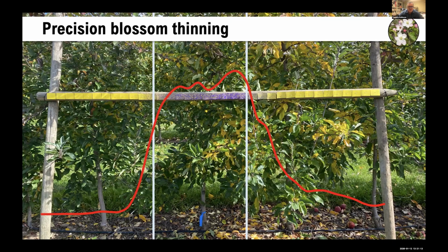And you can see that it turns on right in between two trees. You get most of the tree receiving the full dose, and then it turns off at a little bit slower rate as the sprayer passes. I want to comment that when you're driving 4 miles an hour, the physics of an electronic valve turning on and turning off mean that there will be several centimeters or a foot or whatever of travel distance in the time that the valve is turning on and off.